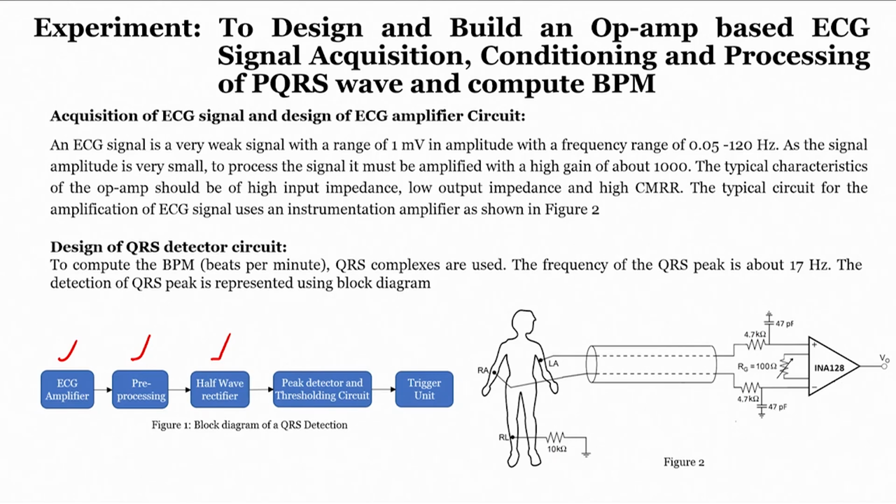If you remember, in case of any rectification, the first and important active element that we take is nothing but our diode. Diode plays a major role, even in case of converting AC to DC. So, one step is our rectification, where by using a diode we convert our AC signal into pulsating DC.